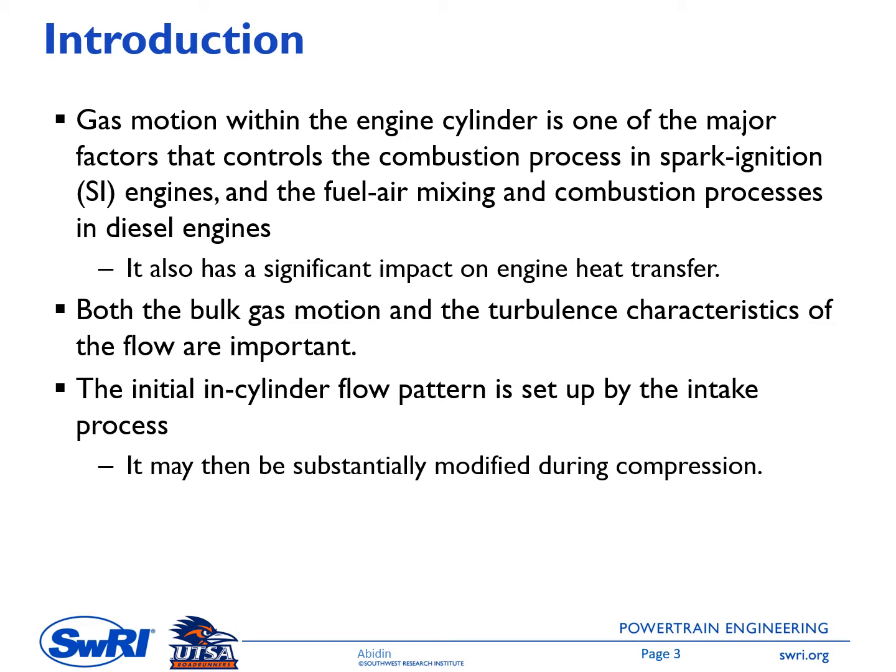Turbulence will enhance the combustion speed multiple times, so we need to have the turbulence as high as possible during the combustion process. Another important point here is to avoid excessive bulk flow around the spark plug to avoid overstretching of the spark, and thus misfire will happen.